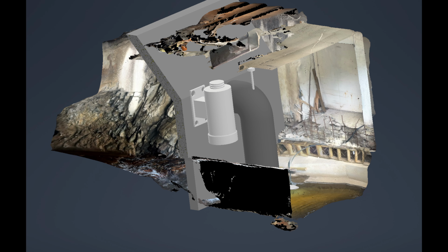The runner's real job now becomes to remove that swirl. Water comes in spinning and leaves straight. The angular momentum you destroyed shows up as torque. On a low head machine, that swirl is your power. Without that, the runner is just a fan in a pipe.